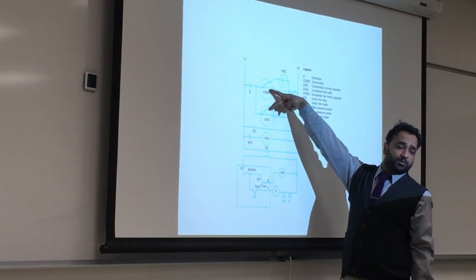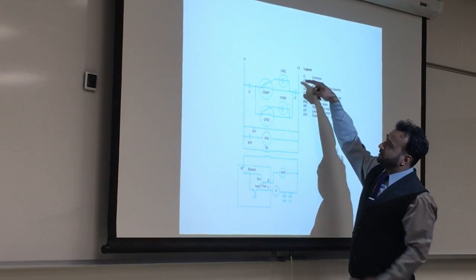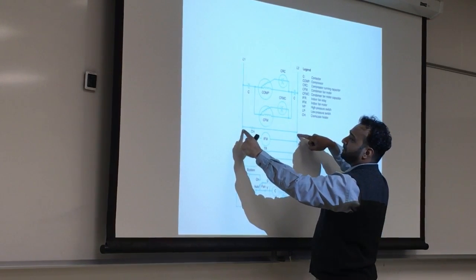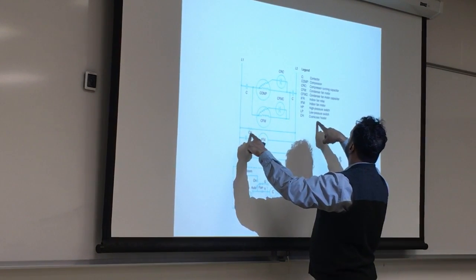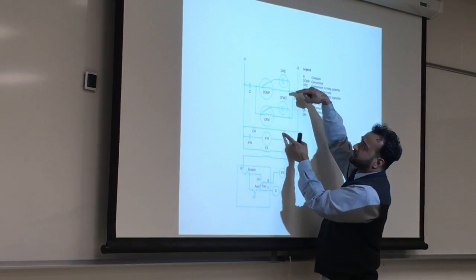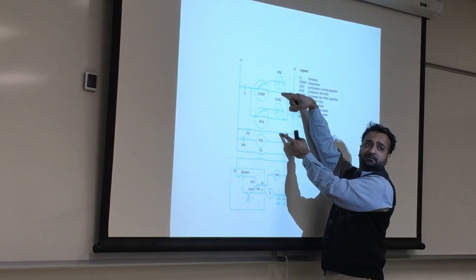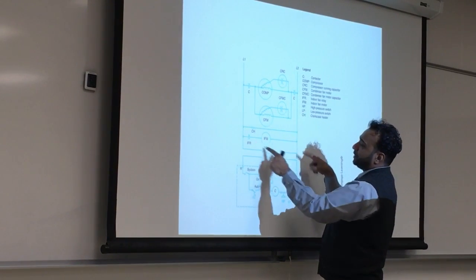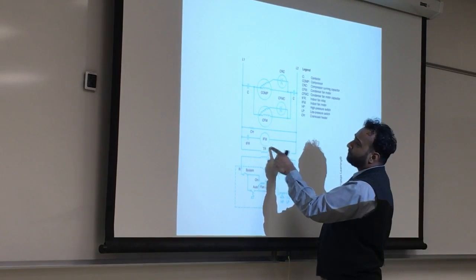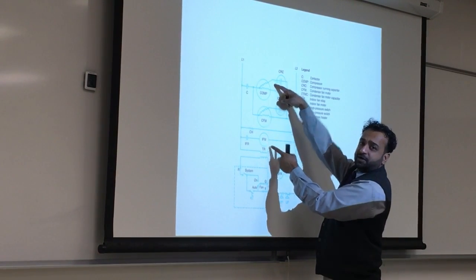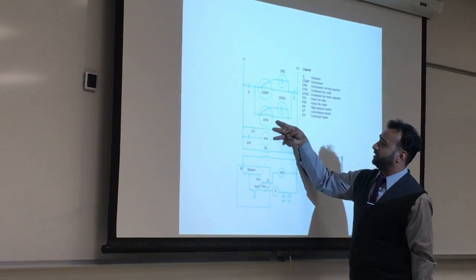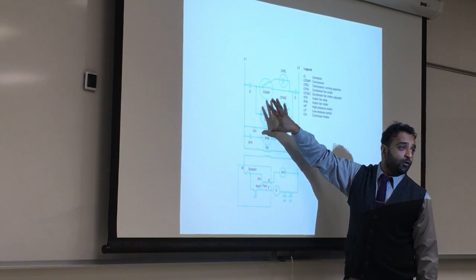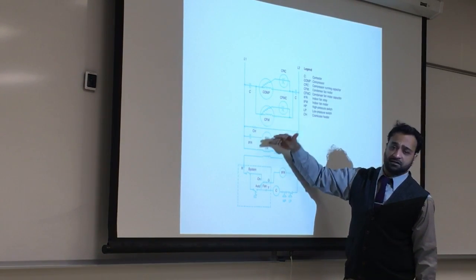So are these connected in series or parallel? Parallel. So this is the first step, which is the compressor. We're done. Second, what do we have? Crankcase heater. Is this and the compressor in series or parallel? Parallel. Excellent. First stage, second stage, third stage. What do we have? And the fan motor. Series or parallel with everything else? Parallel. Loads are always in parallel, so those are three in parallel. Easy so far? Even though it looks kind of overwhelming at first look, it is actually consistent.